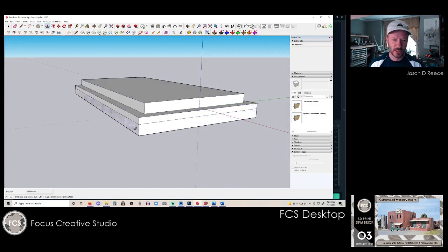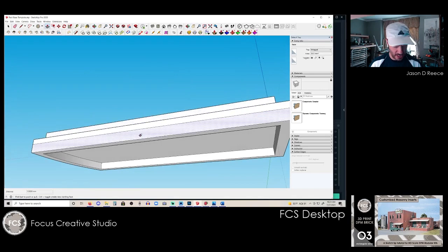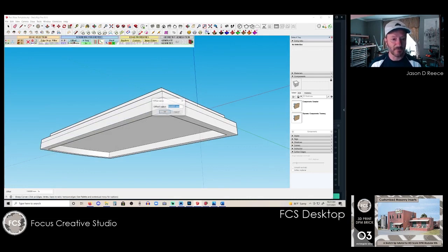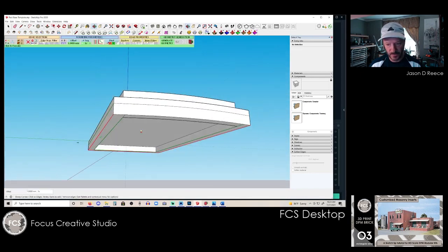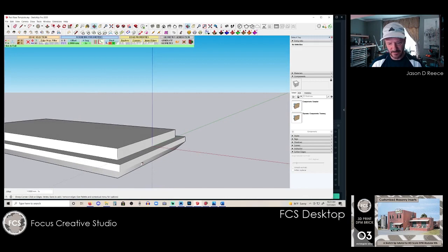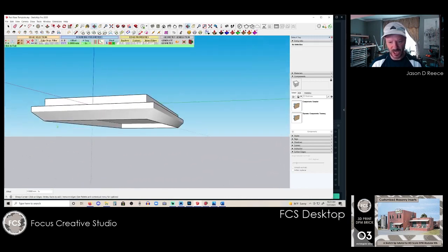I'm going to bevel this piece here. I'll go ahead and I can do that now. Shouldn't have any issues with that. So I'm going to use Fredo's round corner, sharp corner bevel tool. I'm going to set the offset to 1. That'll give me a perfect 45. And then I'm going to select this outside edge all the way around the model, and then hit enter. And now what I've got is a nice, clean, outside tapered edge that allows me to drop supports anywhere I want along the outside here. Easy to clip off and remove when the modeler gets a 3D print that I've created for assembly.